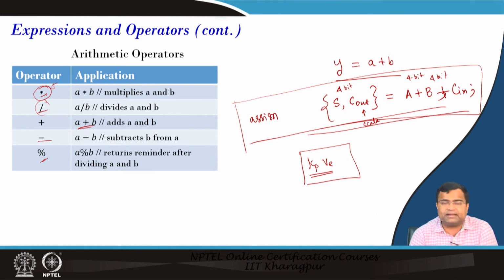In fact, this multiplication is a good example which can be used to differentiate between RISC and CISC architecture. In CISC architecture, the multiplier takes numerous cycles to compute. That's why it is very difficult to do parallelism. But in RISC architecture, the multiplication can be divided into many additions, but you need to store intermediate variables.